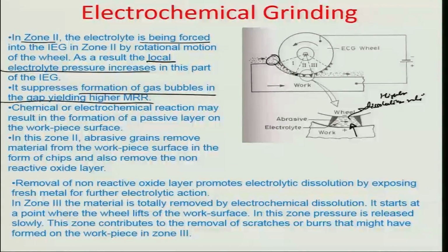Also important is the fact that because of the mechanical action, the non-reactive oxide layer which may sometimes get deposited here because of sludge from the previous zone may promote electrolytic dissolution further by exposing fresh metal to the electrolytic action.